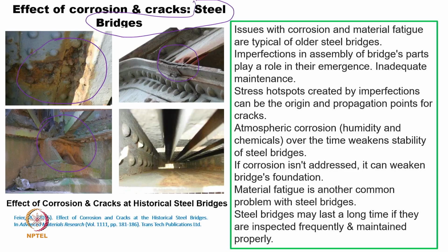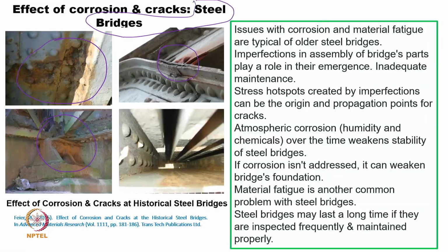When the system is designed initially, many times it comes up perfect, but over a period, even if one nut and bolt gets loosened, there is a shift in the load, and the stress concentration will change. Whatever we initially thought was equally distributed over 10 bolts, if one bolt gets loosened and unfastened, the remaining 9 bolts will get more load. Now, if a second bolt gets unfastened, naturally it will get worse. So this will be a kind of misalignment, a kind of separation, and that is a major problem related to steel bridges, because there are many joints.